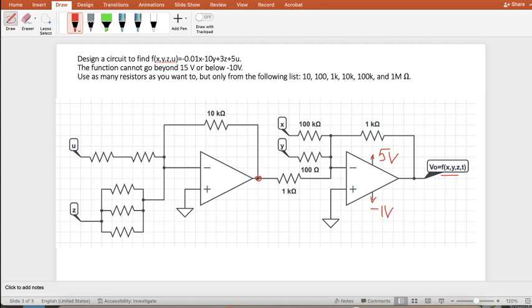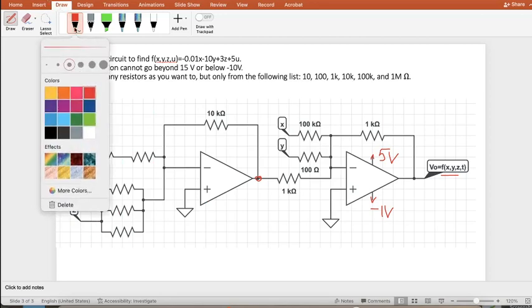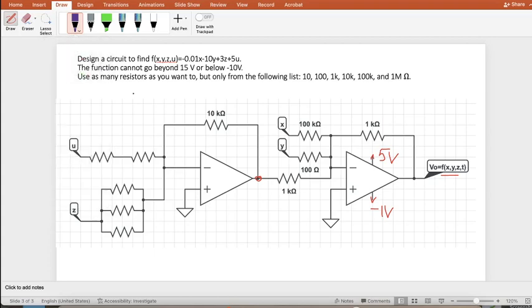So now here I need again to do the u and the z according to those constraints, the 3 and the 5. Instead of the same thing as we did before, I could have used the 1k here, but instead, to make things a little different, I already imposed a 10k on this. So if I want to multiply u by 5, that means this has to be 5 times smaller than 10.